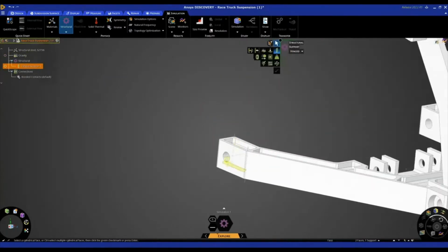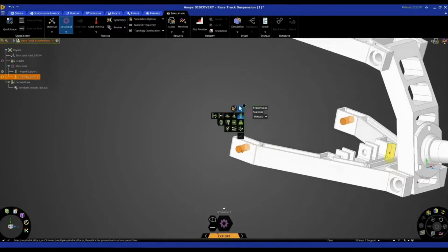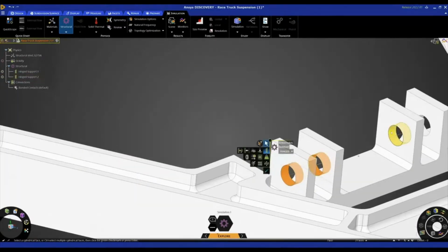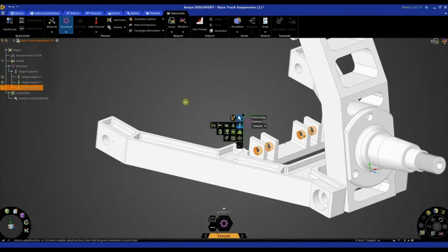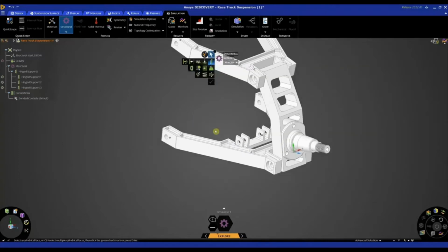So I'm going to apply a few more supports. Let's do one for here and here. And let's do the final one through these 4 pieces down below here. So we've applied our supports as such. And you'll notice that I've applied these coaxially, so obviously we couldn't apply them all together. Only the ones sharing an axis can be applied as hinge supports.